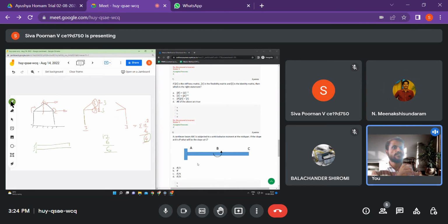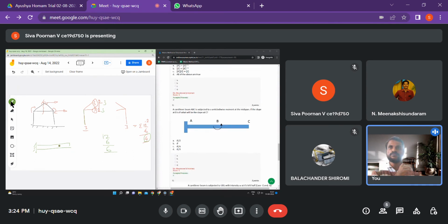Same, yes. It's understandable, because the bending moment is only within this span and not the other span, so the deformation will happen only in that span, and in the rest only displacement will happen, there will be no deformation. So it will be like a rigid body rotation. Okay, so the rotation will be the same. It will not curve, because the bending moment is zero at those points.